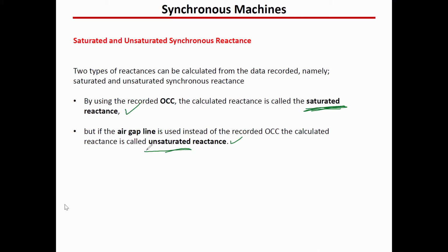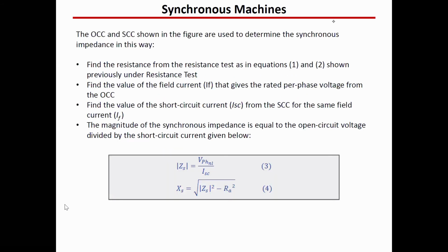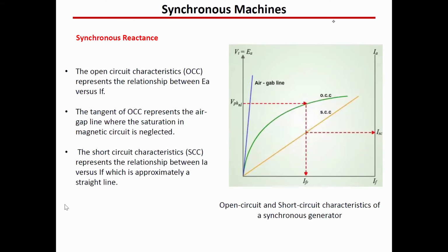Yes, any question? Unsaturated is in the theoretical case, yes, using the air gap line. So if I ask you to find the unsaturated reactance, you use the air gap line, which is the same procedure that I explained before. If I ask you to find the saturated reactance, you use the OCC. So for example, if I ask you to find the unsaturated reactance, it's with the blue line, the blue one, yes.